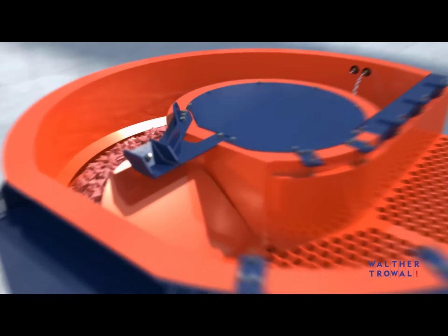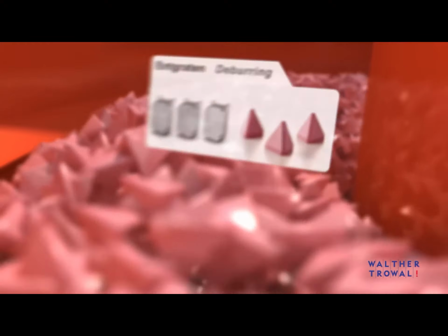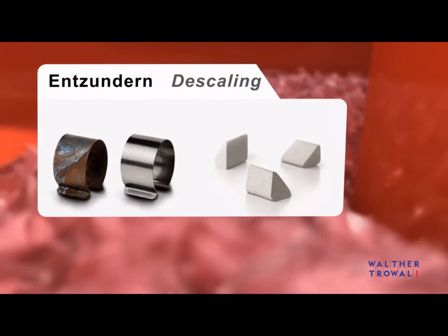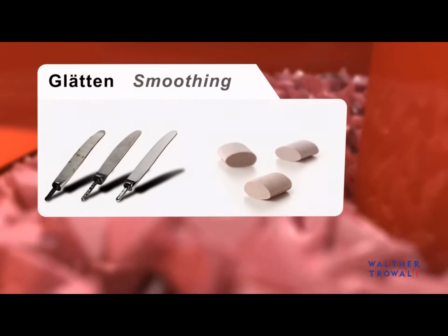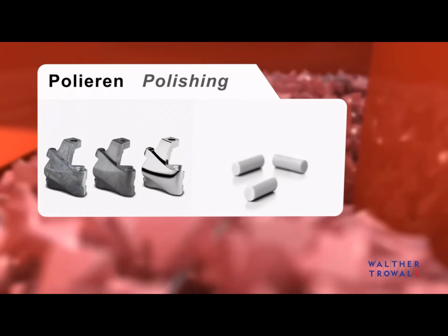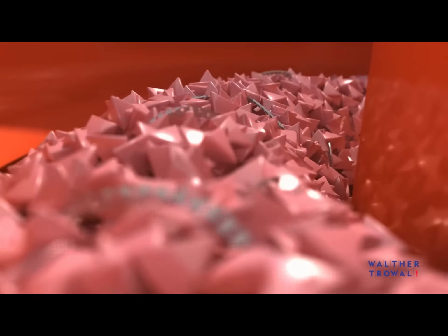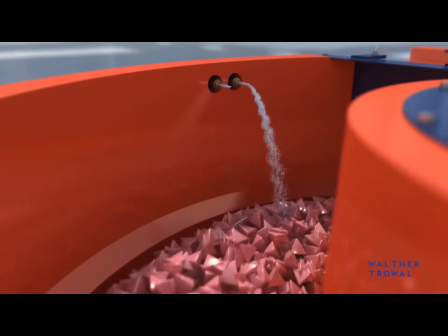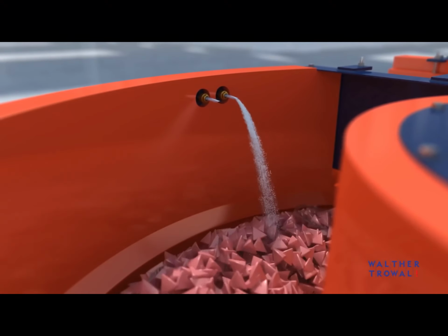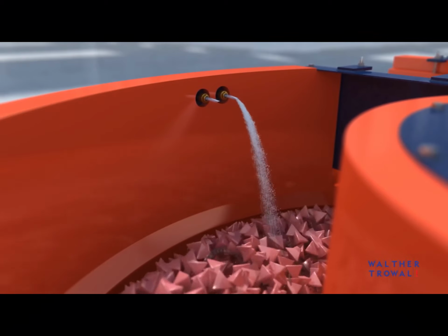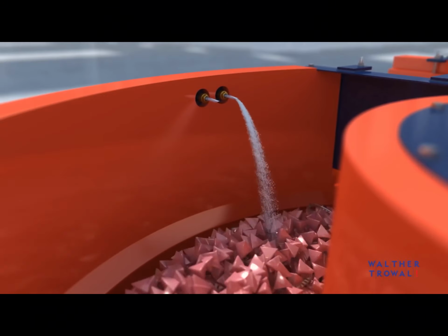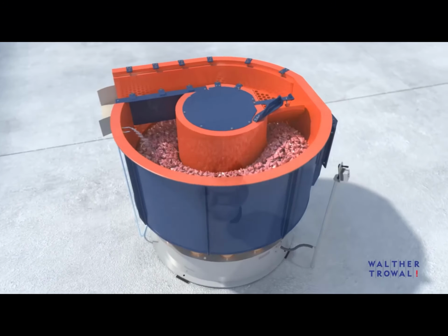The oscillating movement of the processing bowl created by the vibratory drive system causes constant rubbing between the workpieces and the grinding media. This leads to the removal of material, especially from the workpiece edges. The workpieces determine the shape, size, and performance characteristics of the media that must be selected for a particular job. Water and compound are essential ingredients, not only for cleaning and passivating, but also pickling of the workpieces. They also help maintain the abrasivity of the media.